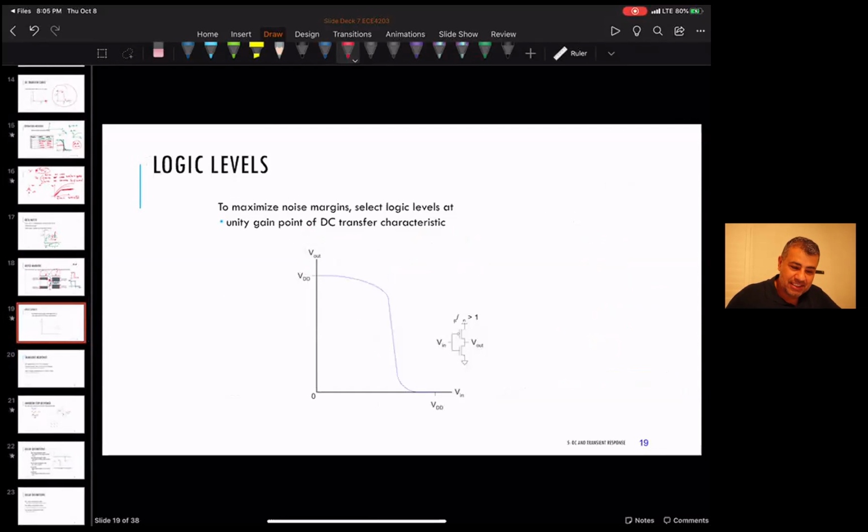So anyway, the way we define the point where we go from the minimum input level, where the transfer function for our noise margins are, is when our transfer function curve goes to a slope of -1.